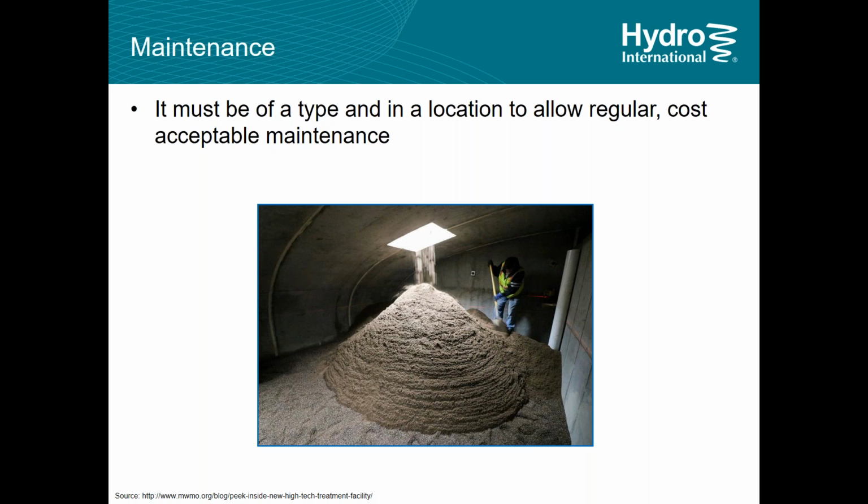There have in the past been many stormwater ponds built and houses put all around them, and now they're coming up after 20 or 30 years for major maintenance, and they find that you actually can't get a truck and an excavator to the stormwater system in the back of people's backyards, and they're having to build new systems to compensate for the development that's gone on. So when we look at these systems, it's critical. Without maintenance, all this falls over. Maintenance is actually the key BMP of the whole system.